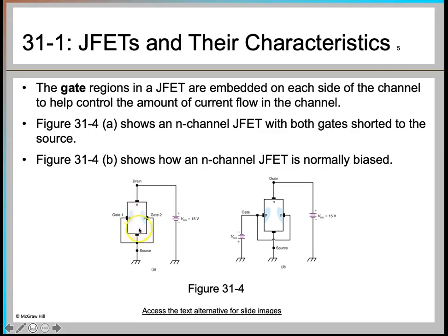Here the resistance is going to be very small, because you see that the depletion region is going like this, the channel is making like this. So here you have the stronger voltage, which means less resistance, and here you have less voltage up here.